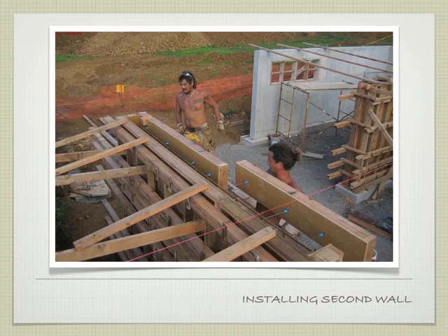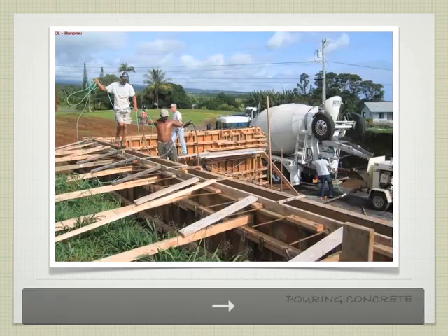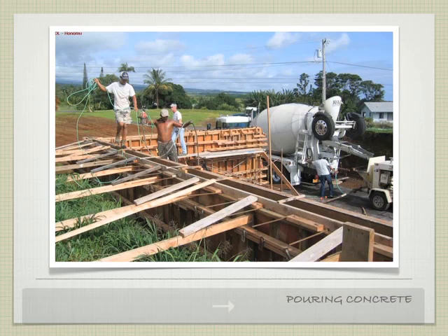There's holes drilled in our formwork. That formwork slides onto these little pieces. We follow that with our studs, our whalers, and finally the little metal bracket to hold it in place. Okay? So we're getting there. We're almost completely formed up. You see there's all our studs. These are our whalers running across. They have a nice working platform, which is good. And we have all our diagonal braces.